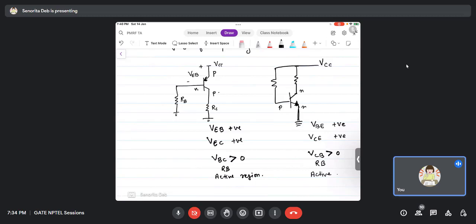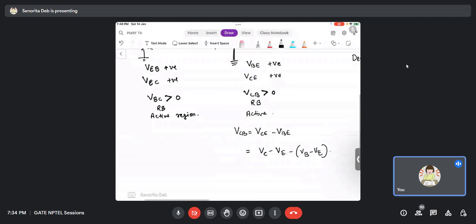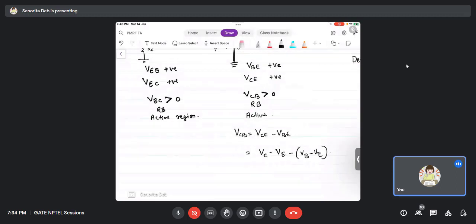And how do you remember this? VCB is nothing but VCE minus VBE, right? And how do you remember that? So VCE is VC minus VE minus of VB minus VE. Okay, so my network is again poor. Just wait for some time. Yeah, so VC minus VE minus VB minus VE. That is how you come to VC minus VB. You got it? Right? And this has to be greater than 0.